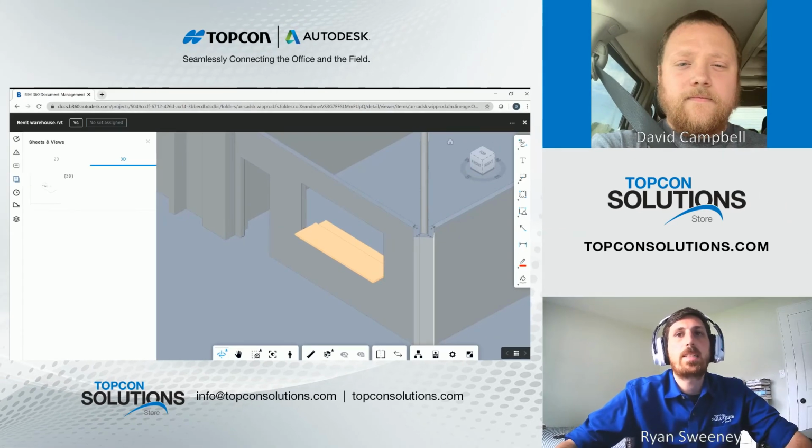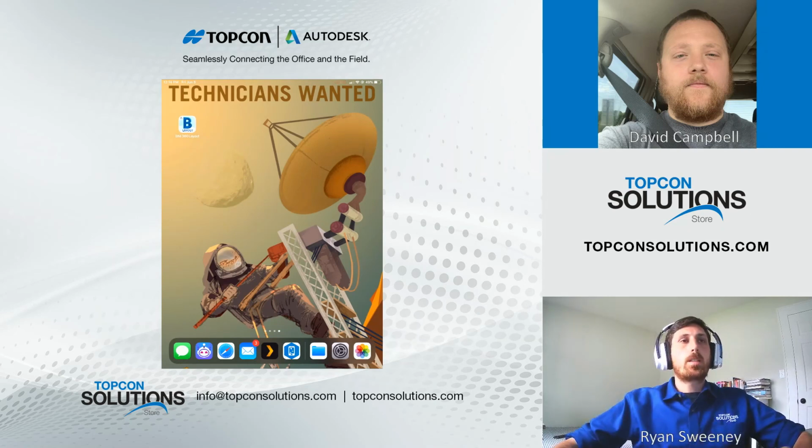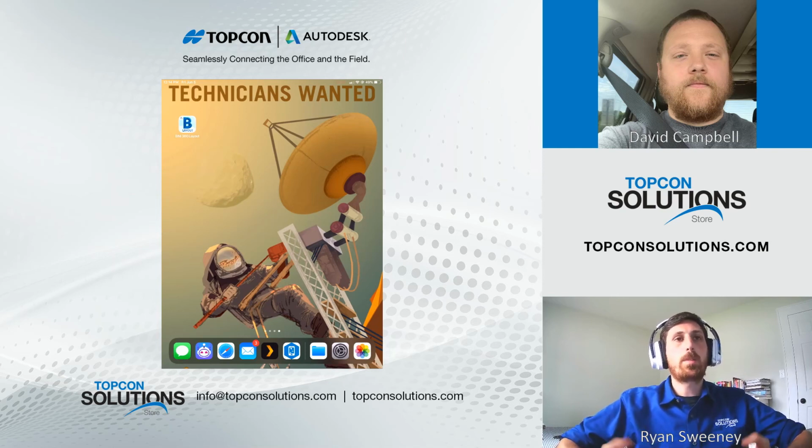Thanks, Dave. I'll be taking over now. So here we go into opening, connecting BIM 360 layout. Now, before going into BIM 360 layout, it always makes it nice and easy if you connect to your total station prior. On an iPhone, it would be going into your settings and using Wi-Fi to connect to the LN series total stations. If you're on Android, you'd be connecting to Bluetooth to the various options you have.